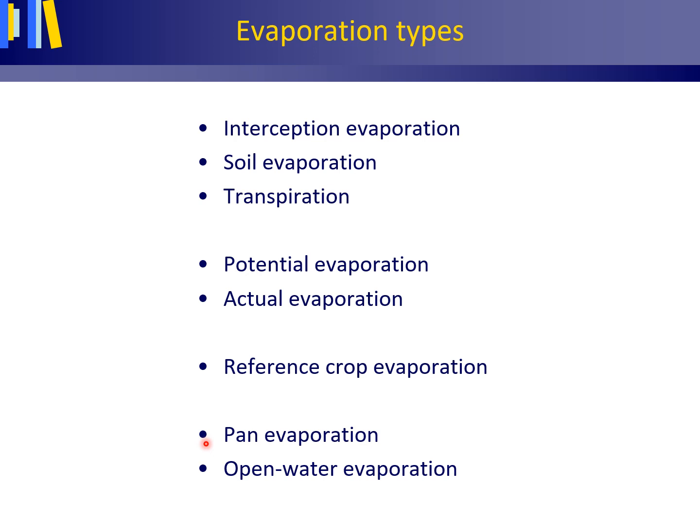The open water evaporation is the rate of liquid water transformation to vapor from open water in millimeter per day. The pan evaporation in millimeter per day will generally be higher than the open water evaporation in millimeter per day from a lake nearby. One of the reasons for this is that the small size of the pan ensures a warming effect of the sides of the pan by solar radiation.